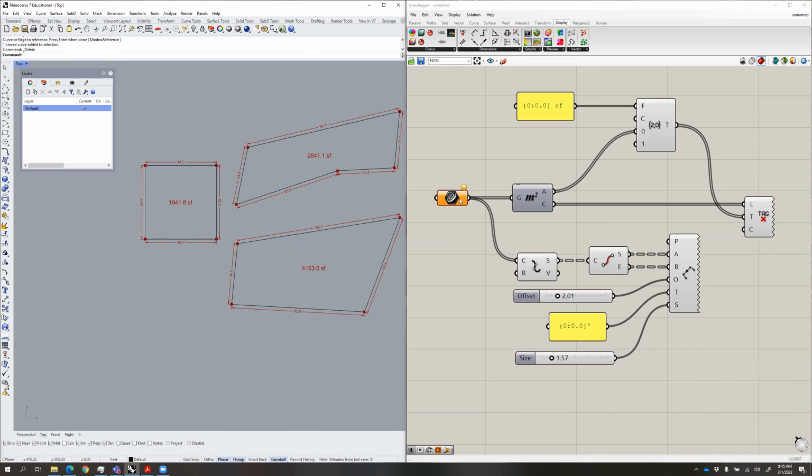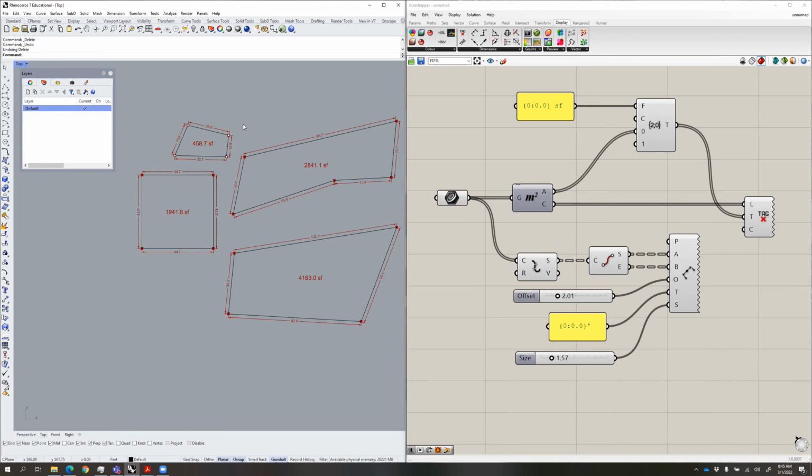What usually happens is that it remembers that you selected it, but it suddenly went missing in Rhino. So it goes orange, as if to say, what happened? Did someone get lost? If that happens, it's just telling you that something happened in Rhino that conflicted with something that's happening in Grasshopper. So you can just undo the deletion in Rhino, and that will fix that.